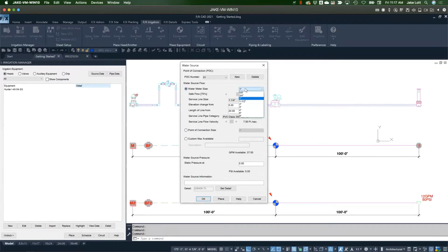So understanding that not only does my water meter size affect the flows that I have, but I also have, again, some standardized numbers here that really match the back of the book numbers for a water meter size and what they have to offer. But you can see that I can start to adjust and utilize more of a safe flow number than what that size of meter can actually do at full-fledged. So this is pretty standard there.